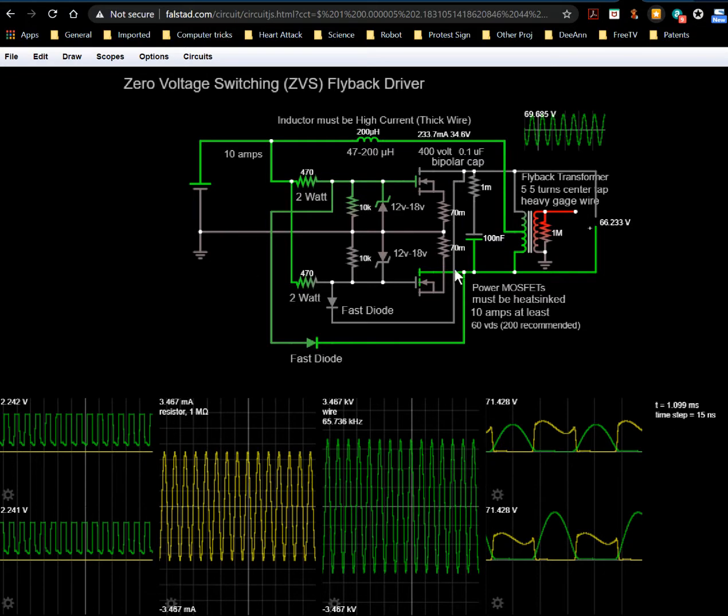But at any rate, the point is you could theoretically control this with just a square wave independent of this and get rid of these diodes. It wouldn't be oscillating, but you would be hard driving it, which wouldn't be very efficient, but you could then control the frequency independently of whatever's going on in this. In fact, theoretically, you wouldn't even need this capacitor. You just need some freewheeling diodes. Don't rely on the body diodes; that's generally not good practice for these. But you need a freewheeling diode across this to eat up the energy, and then you could literally drive this with a square wave.